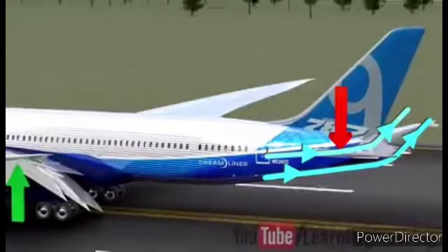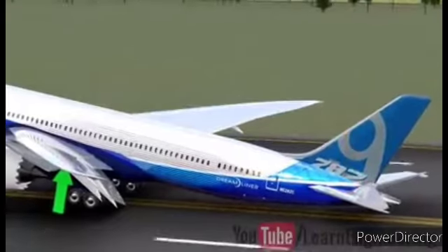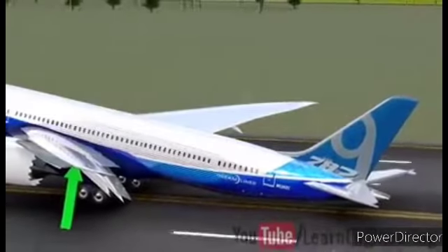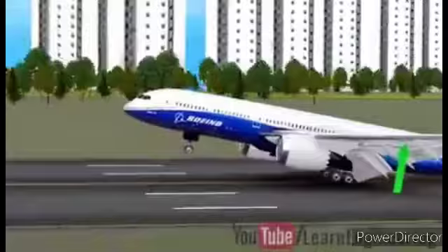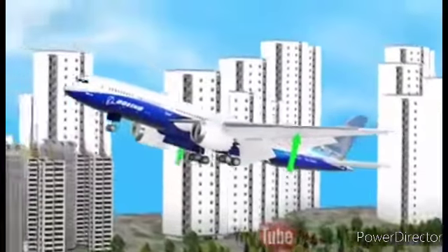The tail force tilts the airplane as shown, and the angle of attack of the airfoil will be increased. The lift is suddenly increased due to this, and the airplane takes off. Usually, an angle of attack of 15 degrees is maintained for the takeoff.